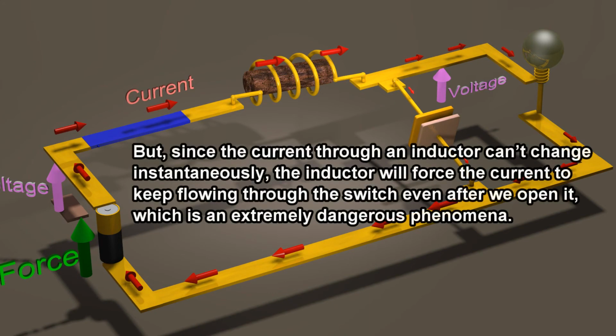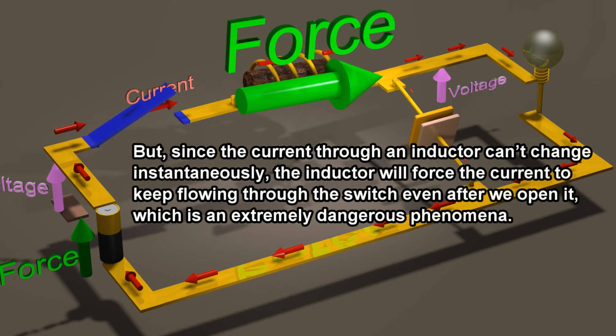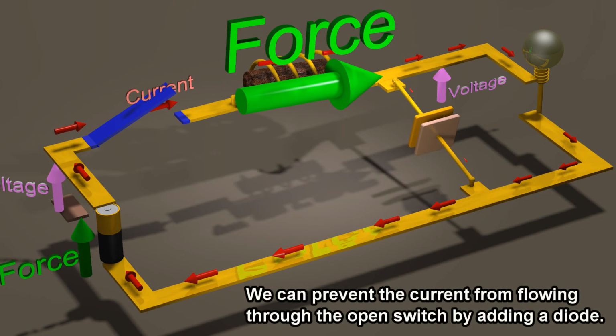But since the current through an inductor can't change instantaneously, the inductor will force the current to keep flowing through the switch even after we open it, which is an extremely dangerous phenomenon. We can prevent the current from flowing through the open switch by adding a diode.